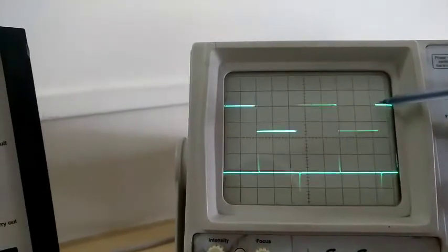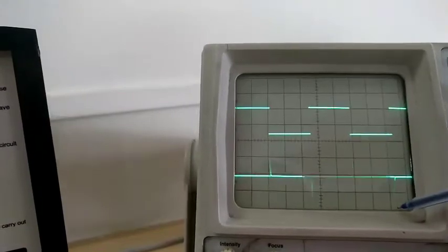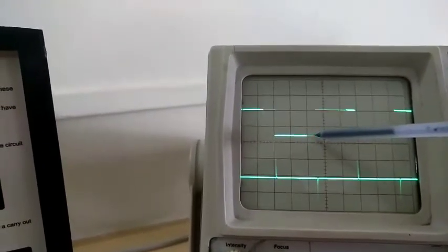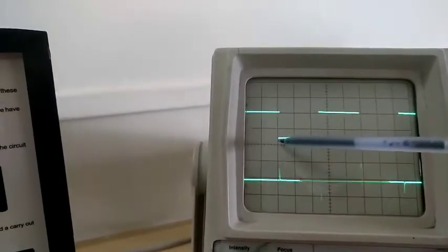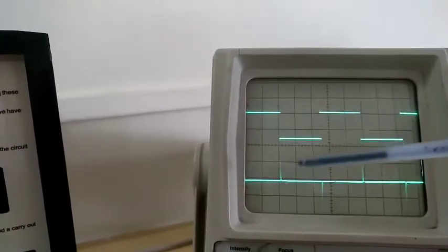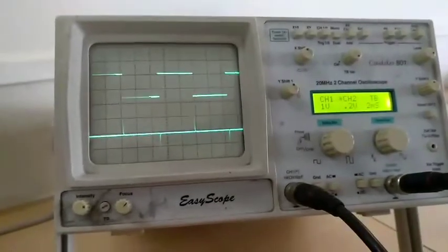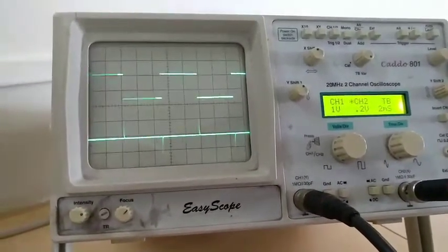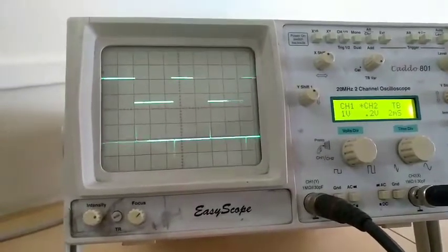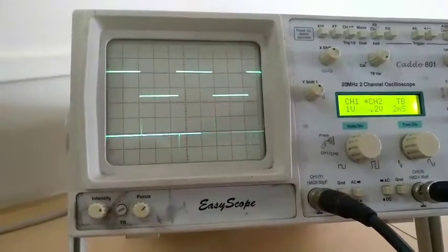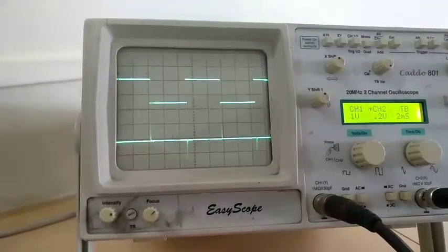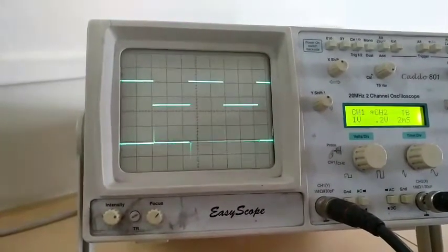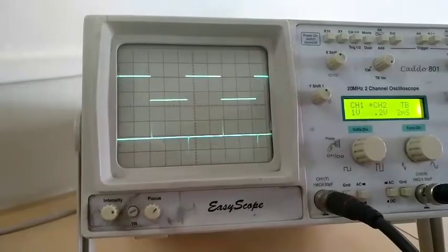So when it goes up, that is a positive transition, we get a negative spike, and when it transits from 1 to 0 level, we get a positive spike. So this is all about experiment number 5, that is the remaining part of experiment number 5, the differentiator circuit. So here we have to just write down that when we are providing a square wave as an input, we are getting a spike at the output.